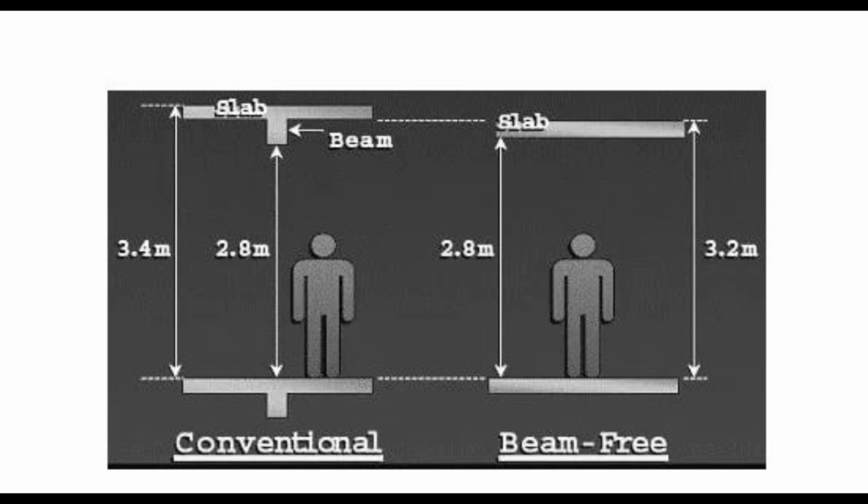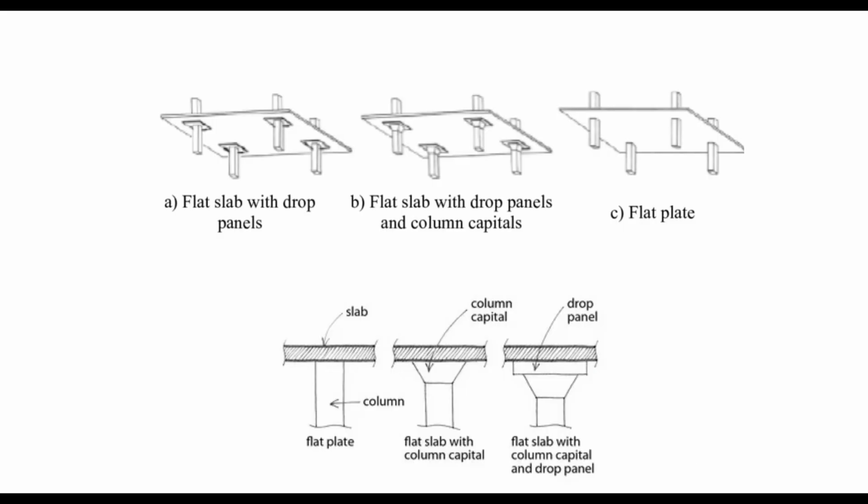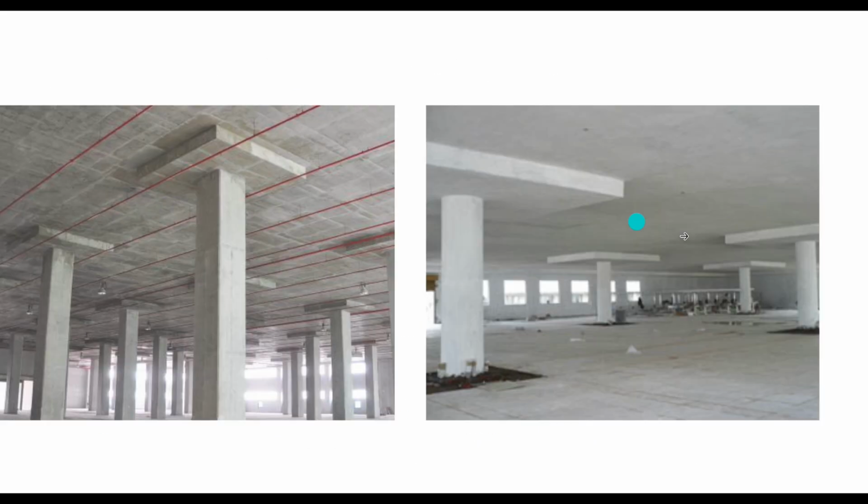The other reason is the spacing between the columns, as I have shown in the photograph. Here, this is very important. The column and slab that you're providing here will continue like this till the end of the project. If you have 5-story, 10-story, they'll continue like this. So if you want to have so much spacing, for example, we can fit 2 or 3 shops in the upper floor over here. In the bottom floor, we have parking, but in the upper floor, we can definitely fit 2 or 3 more shops. Whenever the column comes, it is actually occupying a space.